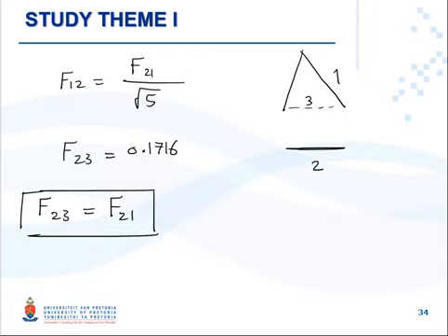Let me explain how. We have surface 2. Let's say radiation is going out of this surface. Because surface 3 works like a gate for surface 1, all the radiation leaving surface 2 striking surface 3 will strike surface 1 as well.